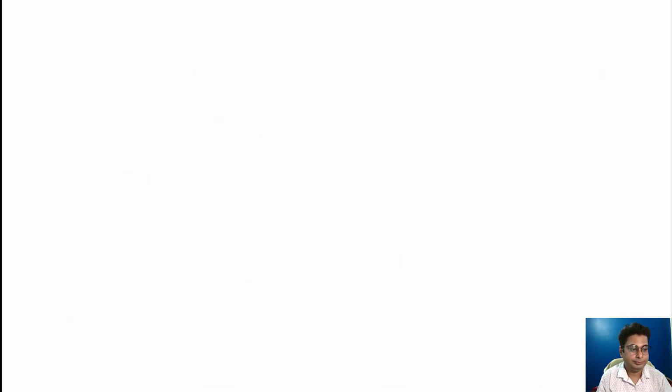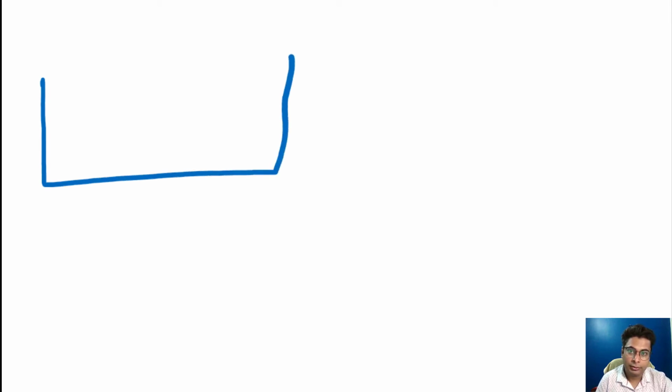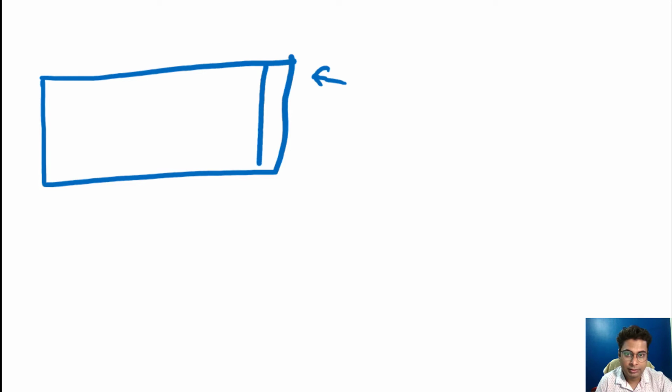see, suppose a shaft like this. First, as we can see, this edge is not straight, so we need to face the workpiece in order to get a very straight edge.